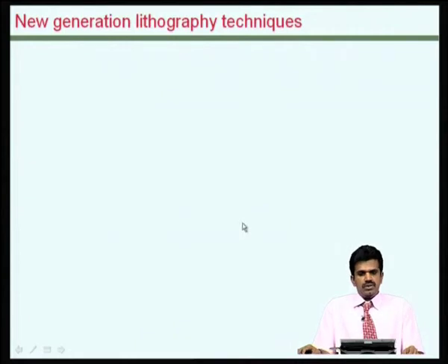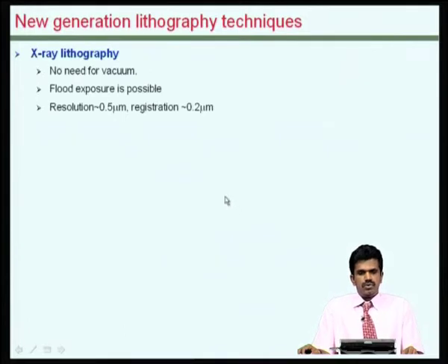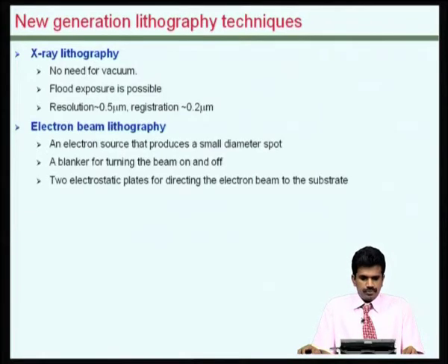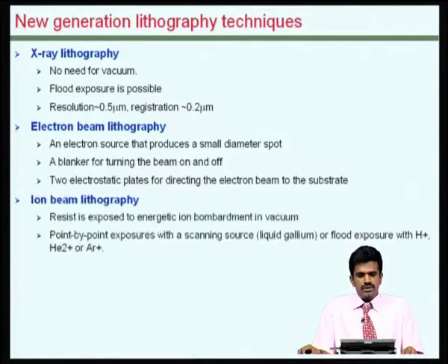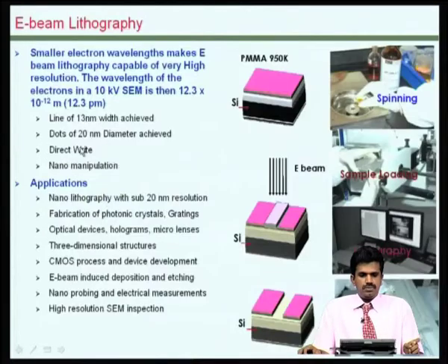There are several new generation techniques used in lithography for high resolution geometries, not so much in the context of microsystems, but usually in the context of sub micrometer technologies for CMOS. It is also possible to use electron beams for patterning layers in these applications. Even ion beams could be used for this purpose.